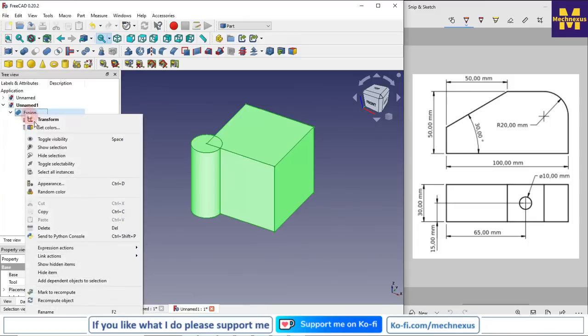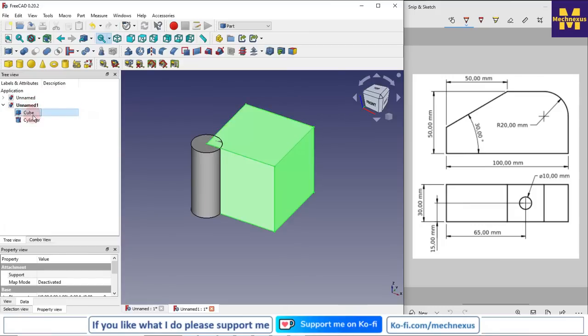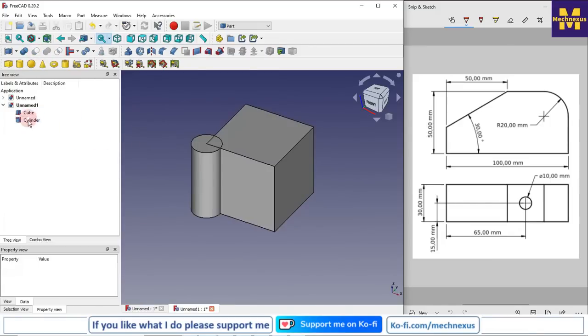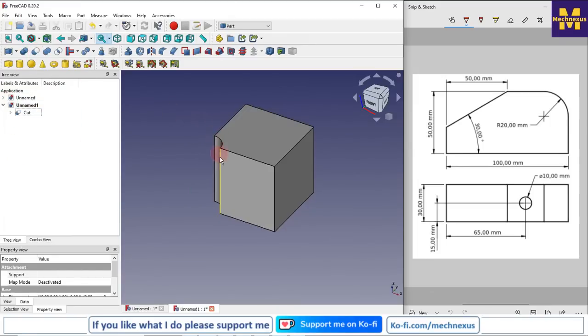Now I will delete this one. Now I will select my cube and then cylinder and click on this cut option. Selection is very important. First you have to select the parent and then the cylinder, because I want to subtract this cylinder from this cube. So I will select cut. You can see that the cylinder has been subtracted from my cube.